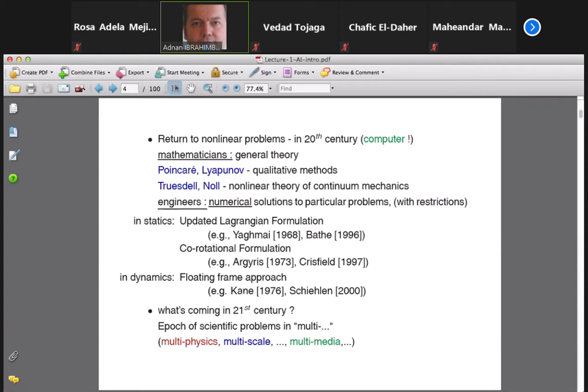In particular, Lyapunov proposed a functional that you have to monitor in order to guarantee stability. And this functional happened to be the total energy. So if your total energy is limited in time, in other words, it does not explode as you go along with the motion, then you're sure that you will have a stable motion.